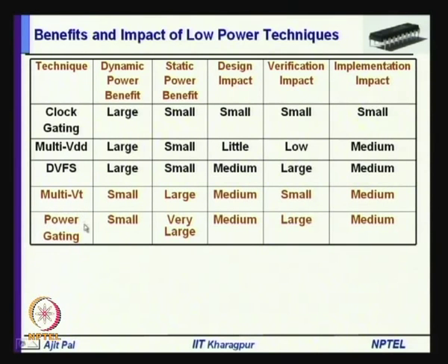Then power gating, which is very important in our present day design. It again has a small impact on dynamic power, because it leads to very small reduction in dynamic power, but it leads to very large reduction in static power, and it has medium impact on design, large impact on verification. It is highly invasive, as we have seen, and it has medium impact on implementation.